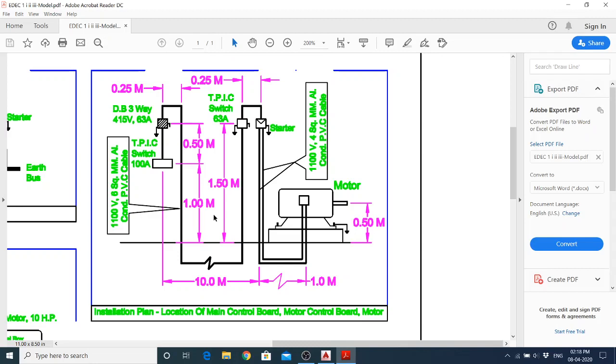That means 20 units are drawn as 1 unit. So it is known as the reduced scale, or you can use 1 is to 25, that is a higher scale, or maybe a lower scale like 1 is to 15 or something. But here I will not draw that way. I will just draw the lines with my own dimensions, and I will mention this dimension after the figure is completed.